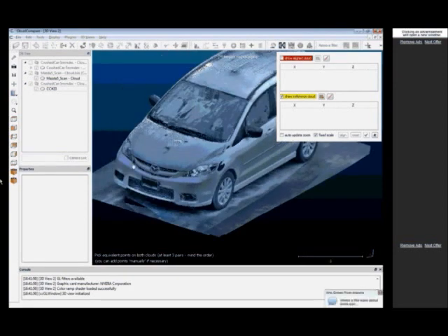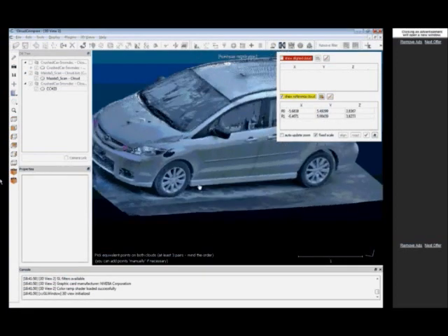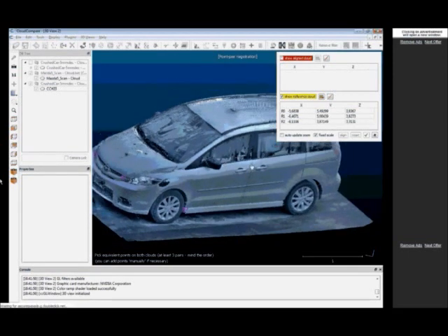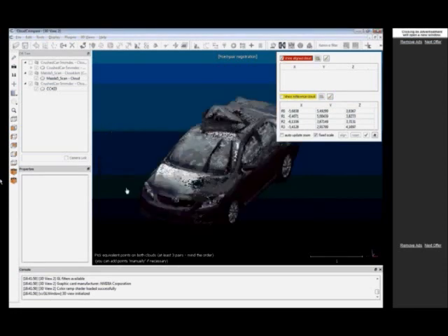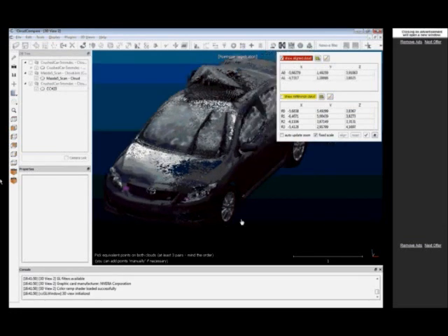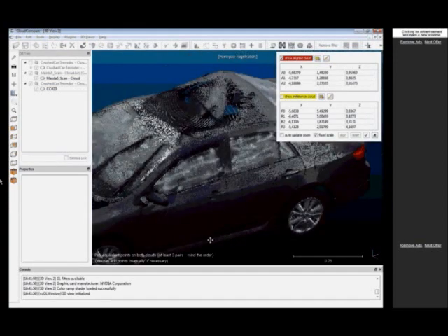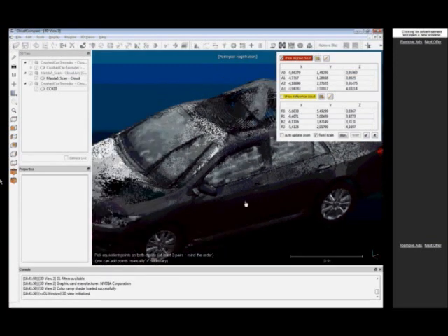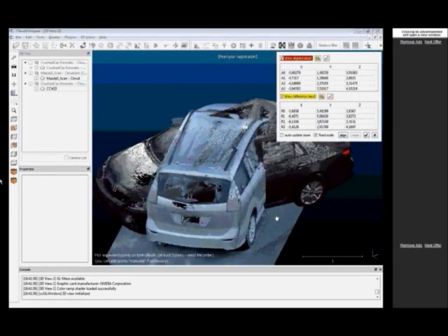Generally at sharp edges, and this one, for instance, and this one. It's just for the demonstration, so I don't need great accuracy. Let me select the same points in the black car. Almost. Anyway, the cars are not the same, so we can't achieve a great registration accuracy. But when I've finished picking my points, I just have to click. I can show both of them. I click on Align, and you see that both have been registered.